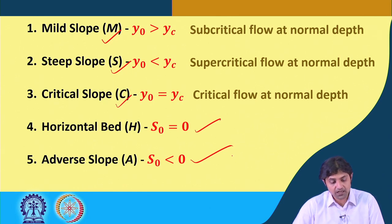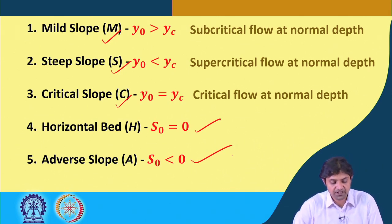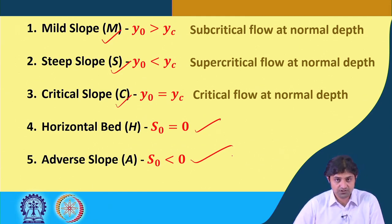One is mild slope channel, steep slope and critical slope, and when the normal depth does not exist, in that case it is simply defined either as the horizontal bed, because there is going to be no normal depth in a horizontal bed, and also in the case of adverse slope when the slope is less than 0. So, it is just defined based on S naught itself, called horizontal bed and adverse slope. Mild slope, steep slope, critical slope, horizontal bed and adverse slope: M, S, C, H and A. So, this is important to remember.